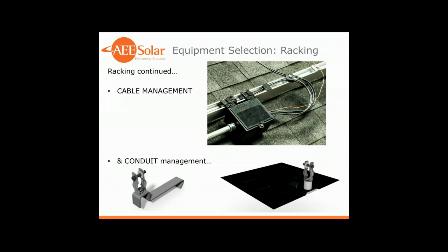So to me, an effective racking system must be UL 2703 listed and tested, and it should also include a strong emphasis on the appropriate cable management and conduit as well. I'd be curious if anybody out there is using any racking hardware that is not UL 2703, meaning they're still cobbling together individual parts and pieces. Now, I fully recognize that your local inspector may not specifically require that, but I'd be curious why you'd be using that system just for your own operation, what the benefits are.